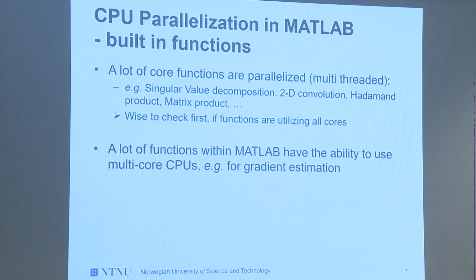A second point is where MATLAB makes it really simple for us. In a lot of cases, for a lot of functions, especially in the optimization toolbox, you can just say, use parallel, and it does it for you. So, for example, if you want to solve a nonlinear system of equations, or you want to optimize and solve for the KKT conditions, you pretty much always have to either provide gradient information, or let MATLAB do it with finite differences. And finite differences, depending on how many variables you have, can be really, really time consuming.